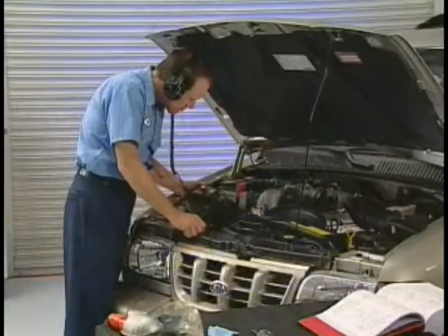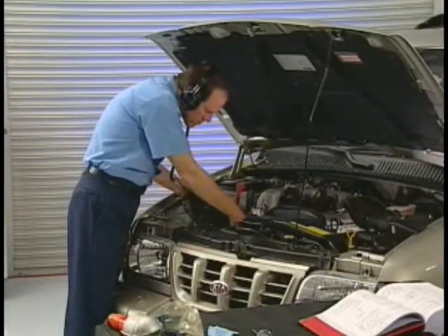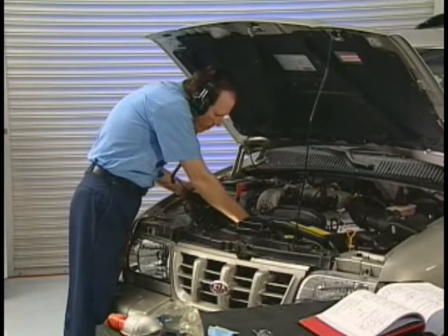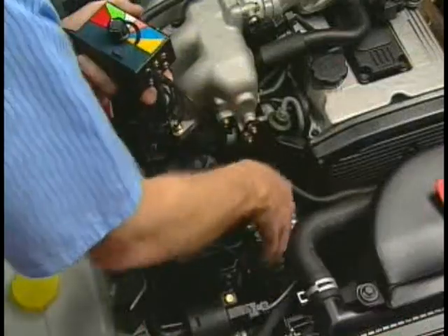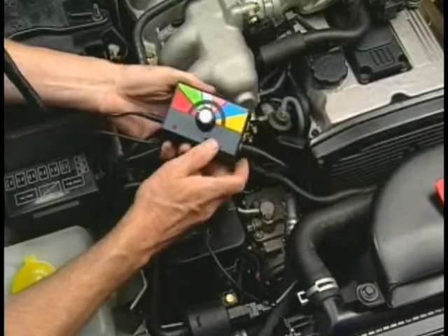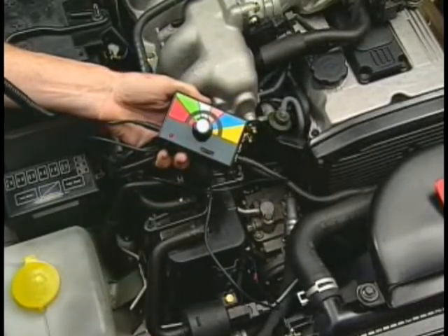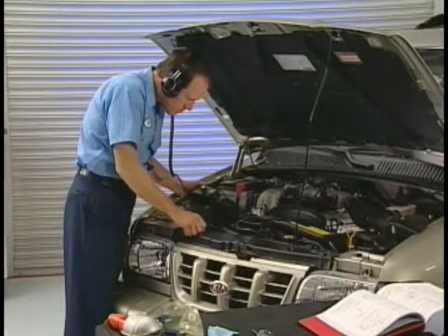Metal-to-metal knocking noises indicate internal compressor damage, and the compressor will have to be either rebuilt or replaced and the system flushed of contamination. A stethoscope or chassis ear can be used to isolate noises that may come from the generator or the power steering or brake assist pumps.